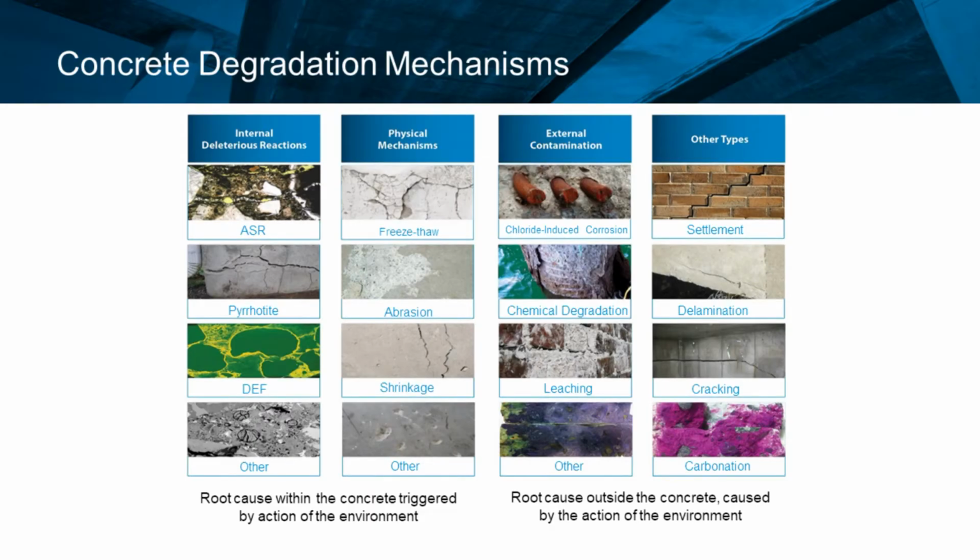There are other kinds of degradation that evolve with time. So now we're talking about external contamination. For example, chlorides penetrate inside the concrete at a given rate, and even if we have the best concrete in the world, it will penetrate more slowly than in bad concrete, but it does progress with time, and in that case, it's good to figure out how fast it goes to know when problems can be expected.